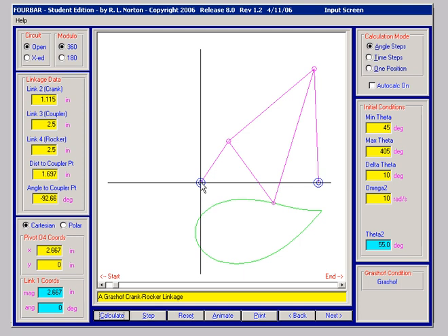I'd call this O2, or possibly instance center 1-2. Link 3, as I said, has some dimension to it other than just a line, and that creates what's referred to as a coupler point right here. And that coupler point is defined, for the sake of the program, by two dimensions. In this case, they are polar notation, and that's your only choice.